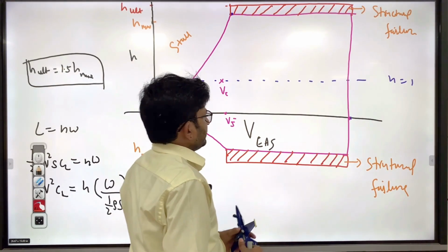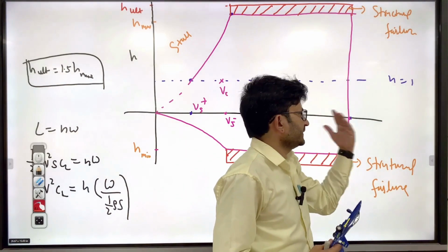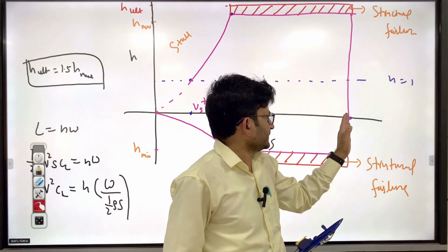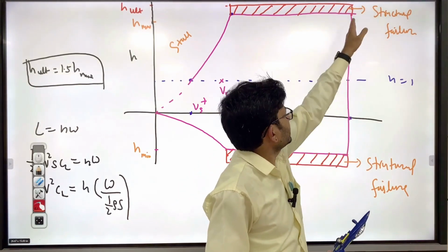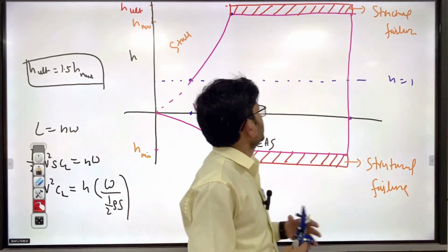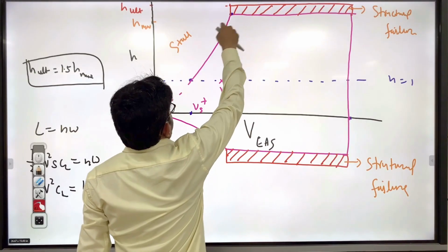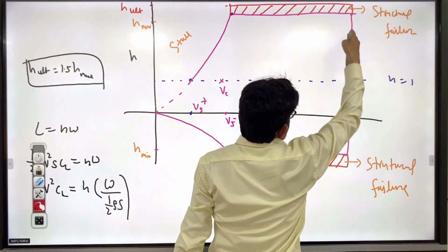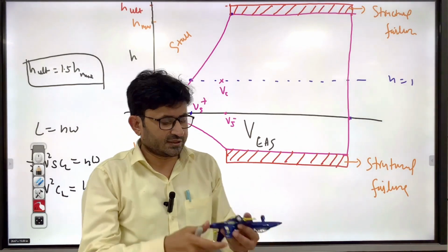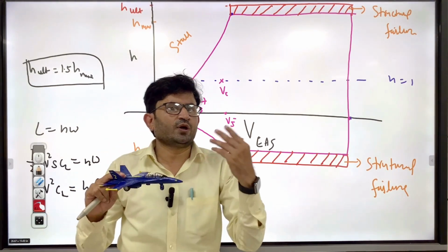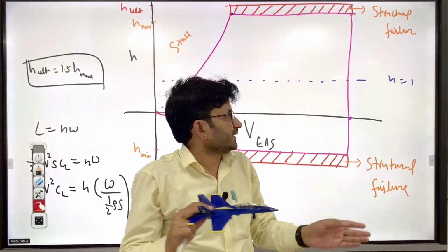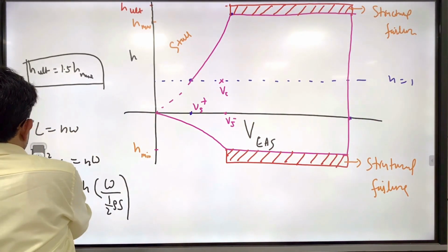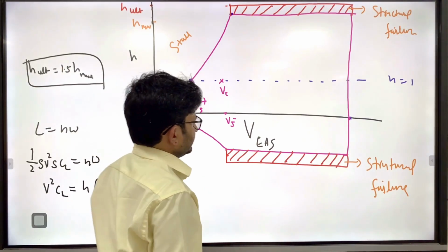And if you are flying at a particular altitude, let's say at sea level, you cannot go beyond one particular speed. So you can draw this line. This is the propulsion limit. This is the aerodynamic limit: positive stall, negative stall. This is the structural limit. And sometimes it happens that you are diving, so you cannot dive beyond the allowable dive speed. That limit you can put here. So I think the VN diagram part is clear, and how it has been drawn is also clear, right?